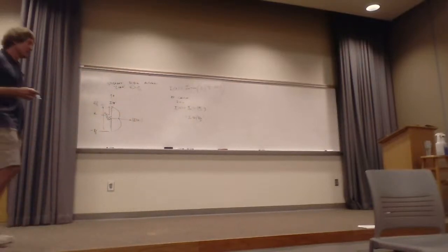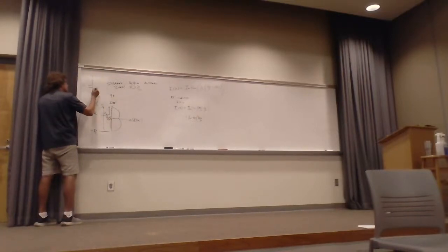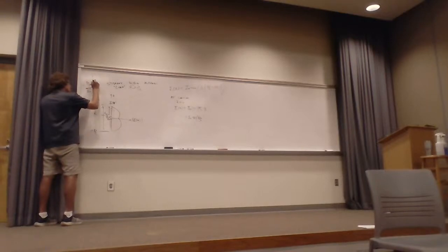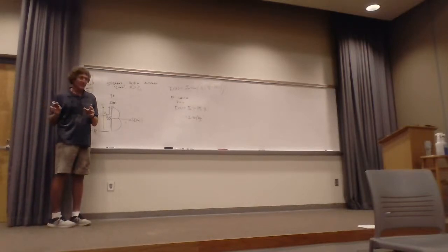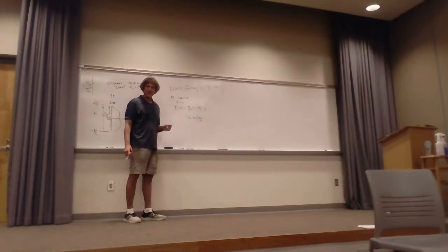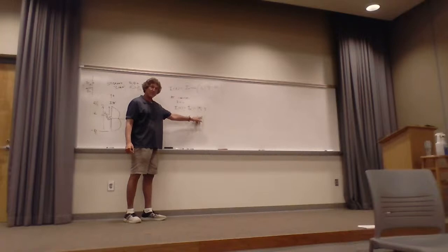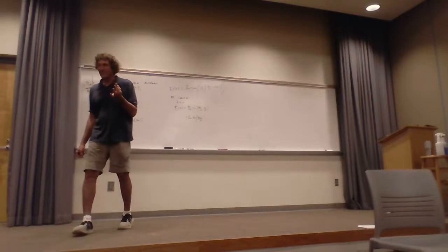Okay. Now, what you would say is if you have an antenna like this, then the current here, I naught, should be the current right here, just as you turn that bend, right? That's intuitively what you'd say. Not quite true. Take a look at what happens. Suppose L is equal to lambda. Now the total length of the antenna is 1 lambda. Then I get lambda over lambda is 1, correct? And I have the sine of pi. What's the sine of pi? 0.